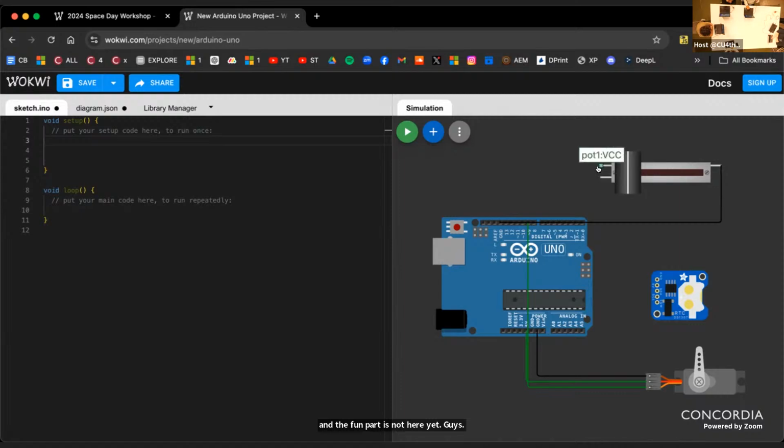So you go to the VCC, which is kind of like the V+, it's just power. You connect that to also power, also the 5 volt. Yeah. And signal, the SIG port, that one's staying 0, I believe. It goes to this pin, and it's a little bit more technical, but we don't need to explain it. You'll see how it works.